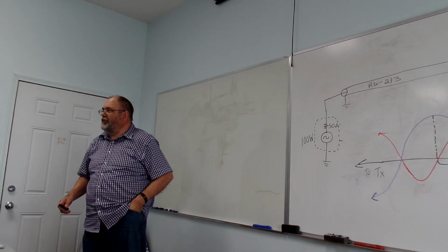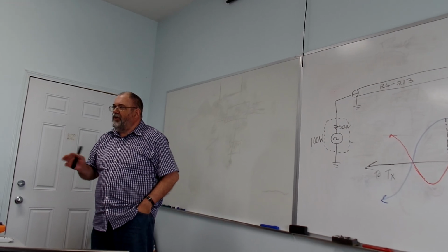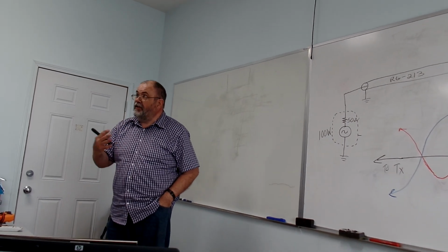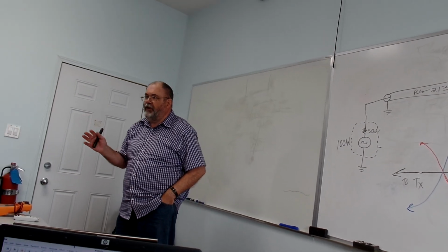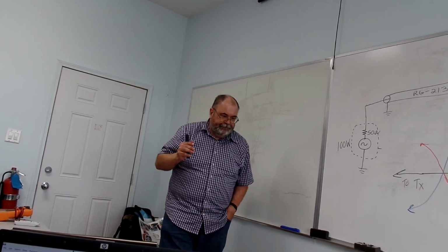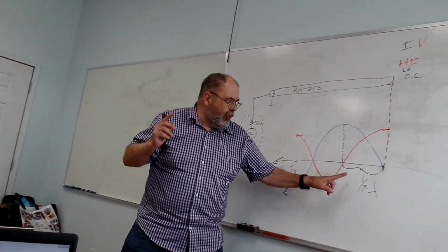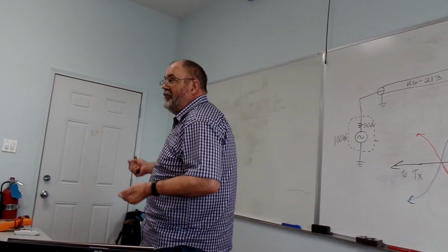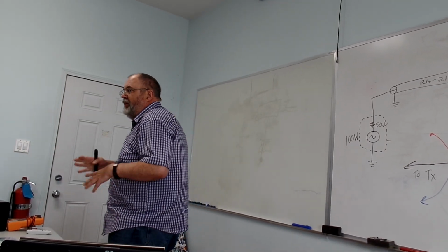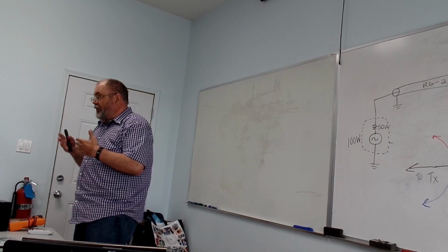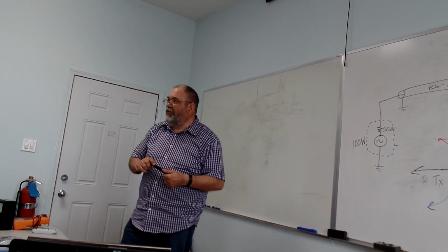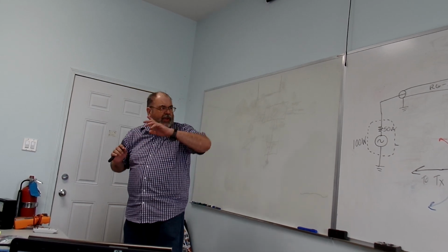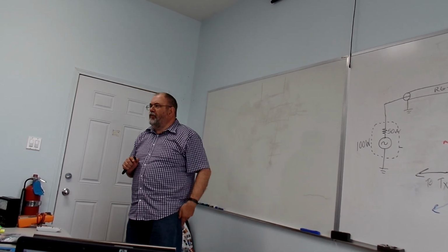It's a fun thing to understand. Some people, as I mentioned earlier, kind of intuitively get it, and other people just go, well, that's beyond me. But if you can remember, a quarter of a wavelength will reverse what's happening on a transmission line. We haven't said at what frequency. It doesn't matter what frequency. It's a quarter of a wavelength. Will reverse what's going on. So why in the hell would you ever want to do that?